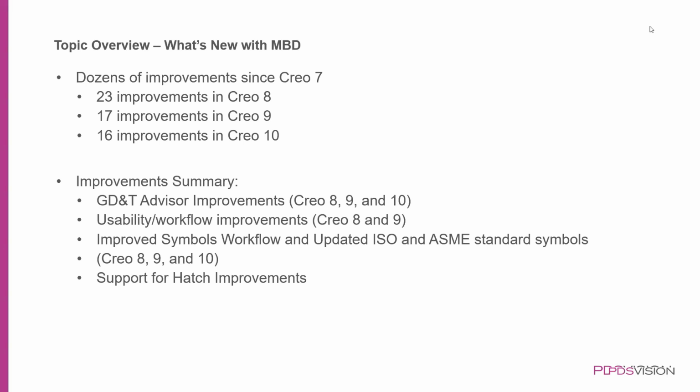It's going to allow you to implement GD&T across an entire model, excluding certain surfaces, and that will be parametric. So if you add additional specifications to a surface, then that surface will not be included in the overall anymore. So it really greatly improves the intelligence of GD&T, how they're able to update with changes to your model, and can help reduce error by finding syntax errors as you create them.